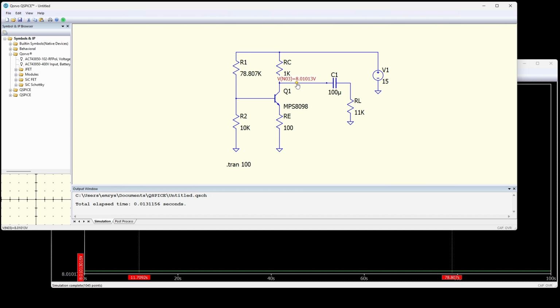Remember, this is an amplifier, so the whole point is your output is going to be varying up and down depending on how your input varies. So you want to have as much room above and below this midpoint voltage as possible for your signal to travel. Also, your signal being in the middle means that you're going to have better linearity from the input to the output.